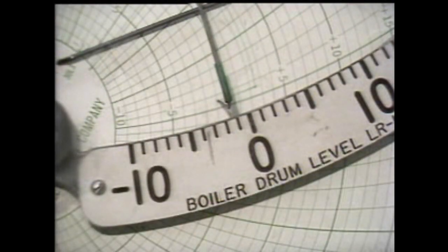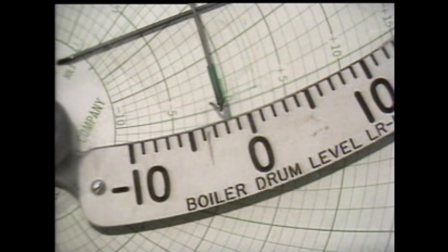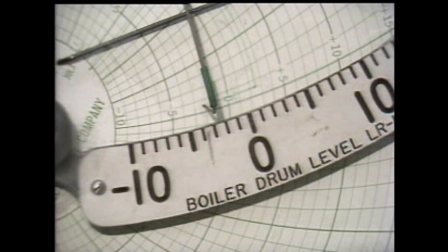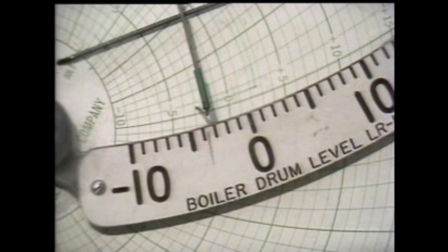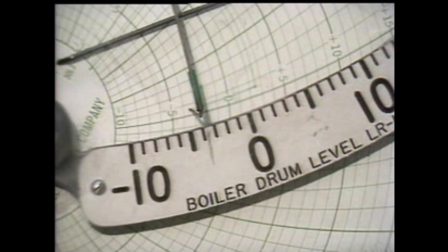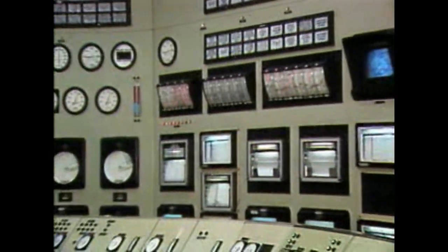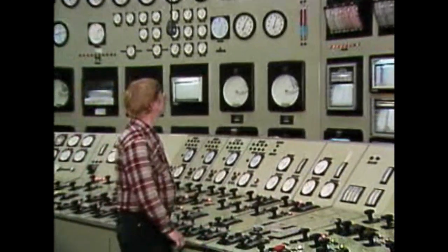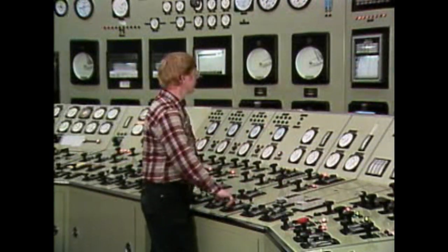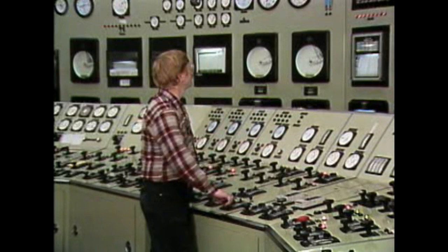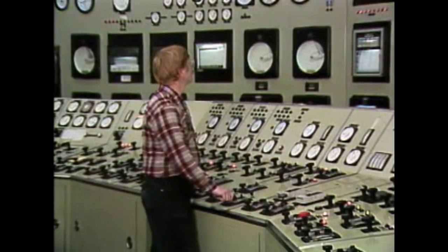To find out what caused the alarm, the operator must check other indicators to determine the status of the system involved and any associated support systems. Then he can take the next step, putting the plant in a safe condition. If there is immediate danger, the operator must take immediate action to protect equipment and personnel. At this point, the emergency has been handled, but there's a third step. The plant must be returned to normal.